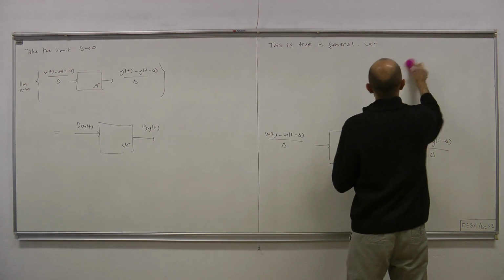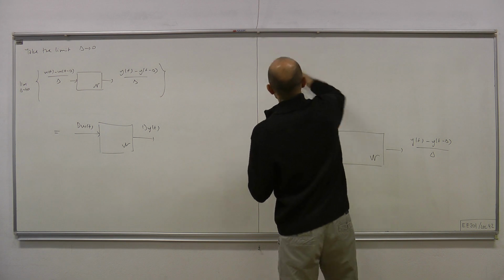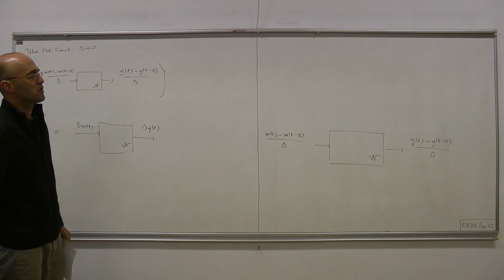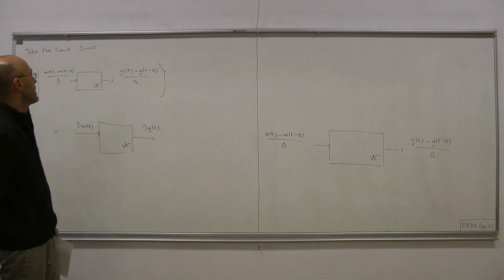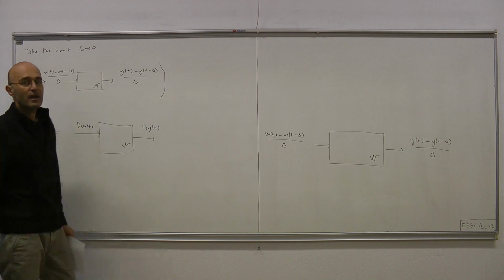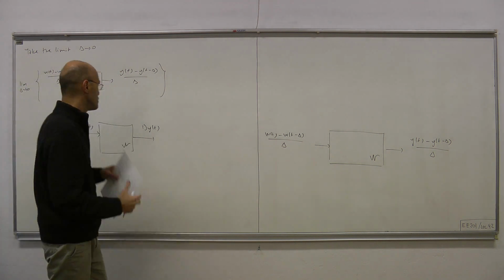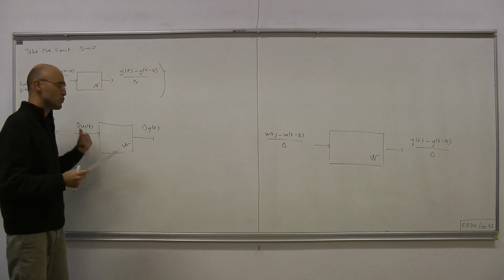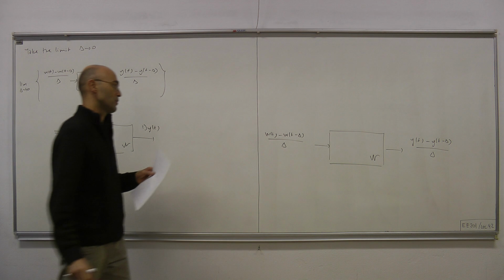So therefore, we discovered something quite remarkable and in a very easy way, only using time invariance and homogeneity. And what we obtained is that this derivative operator behaves just like a scalar. Okay, so homogeneity can be extended, can be generalized to such operators, for LTI circuits.